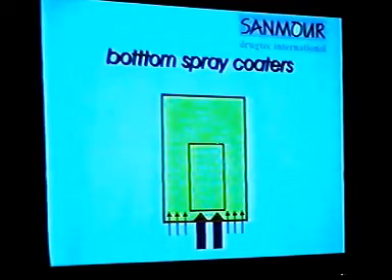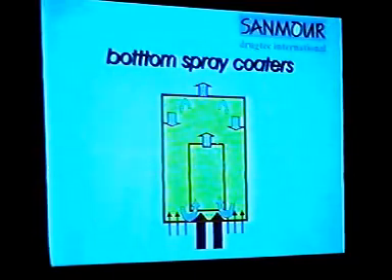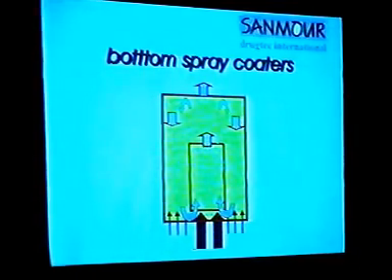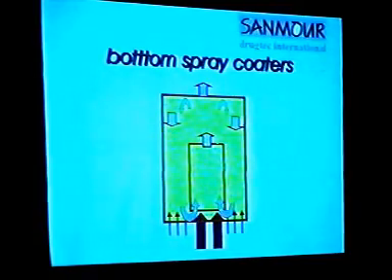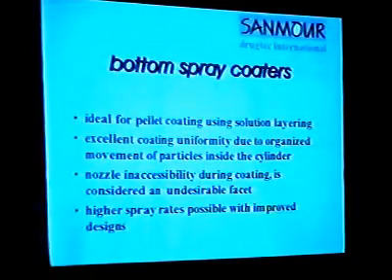This is the main product chamber we are seeing, and then the booster chamber. And you see there the arrows indicating the movement of pellets within the booster and outside the booster. The idea is to maximize the population of pellets within the booster chamber, so thereby you can increase the spray rate and achieve much shortened process timing.